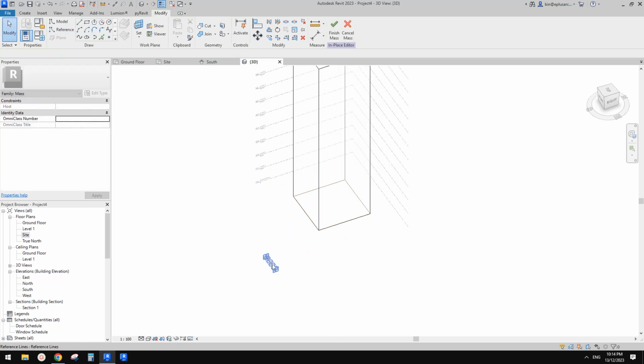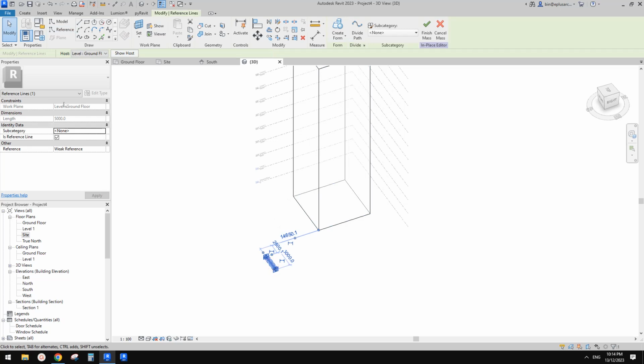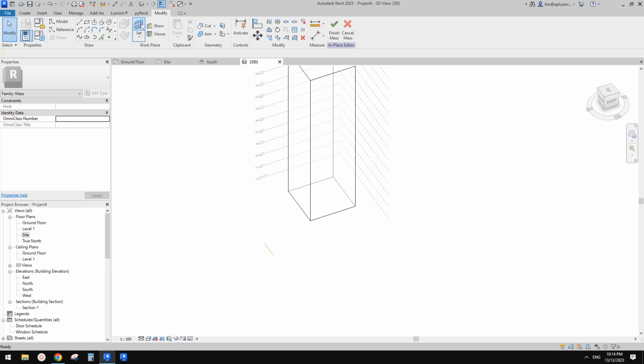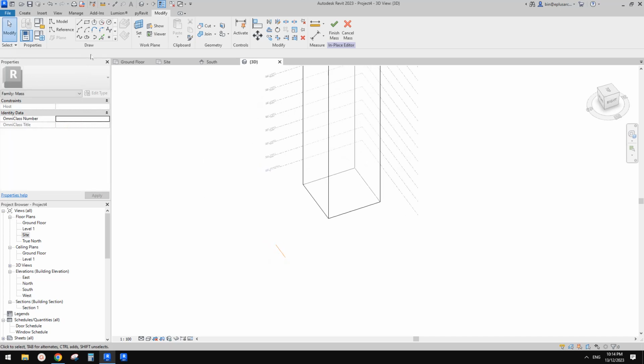So I'm going to just create it on this ground level, currently ground level, and then I'm going to set world plan. Okay, and then hang on, let me think. Set world plan, yes. Pick reference line, yes. So this one, yes, so that's correct actually. And then I'm going to create a half circle. So use center and arc.